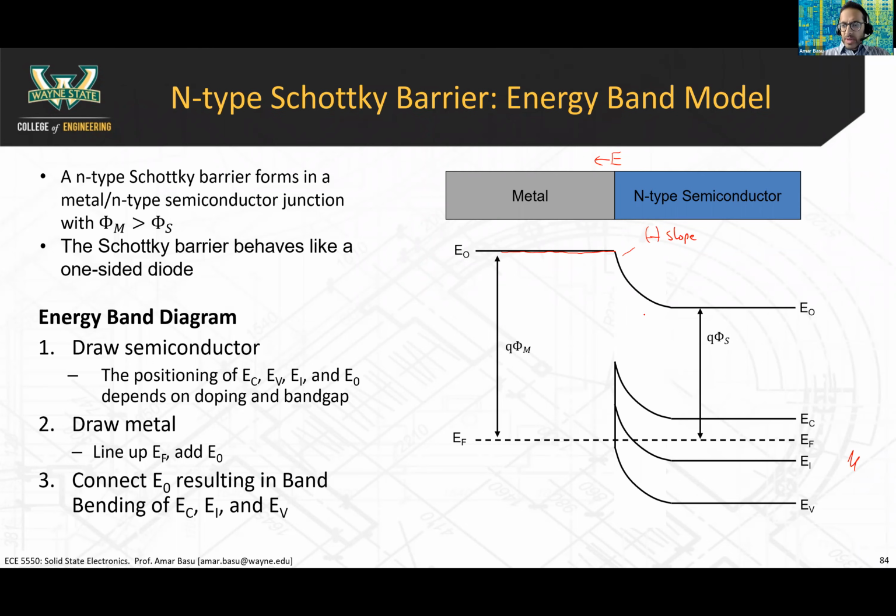But before we get into the details of that, just to finish up this diagram, there is a depletion region here. There's an electric field. And just like a PN junction, at some point the depletion region ends and the band is horizontal again, like this. That is referred to as a neutral region. Again, we're going to get into the physics of the depletion region in just a second, but let's analyze what's happening from an energy band diagram standpoint.